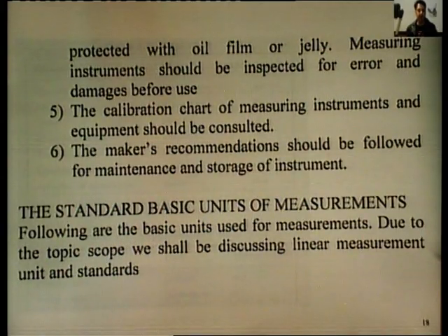So the micrometer is a very sensitive instrument, as all of you must be aware, and you must have seen this micrometer. There is a ratchet provided on one end of the micrometer on the thimble side. We use this ratchet and rotate it so that the pressure created on the job is not very high, and so that the pitch of the screw does not change or get damaged, the threads.